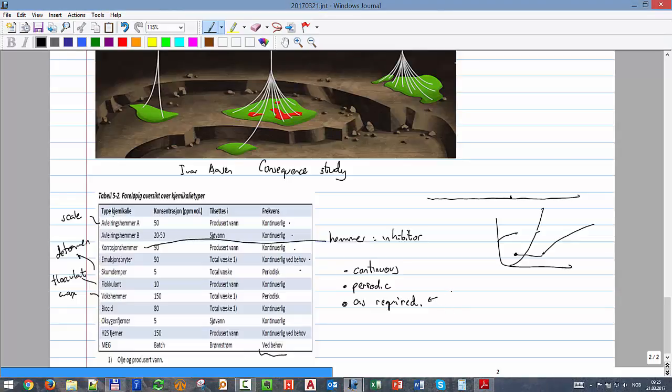Okay, so that's specifically, for example, also used to remove scale deposit, or also during shutdown periods. Like for example wax, that's hydrate and wax. Wax, due to the gelling. If you have a problem that you could have gelling, then you have to inject this pour point depressant to be sure that it won't make almost like a solid in the pipe, but it will still be allowed to flow after some time. And the hydrate is also the same idea.